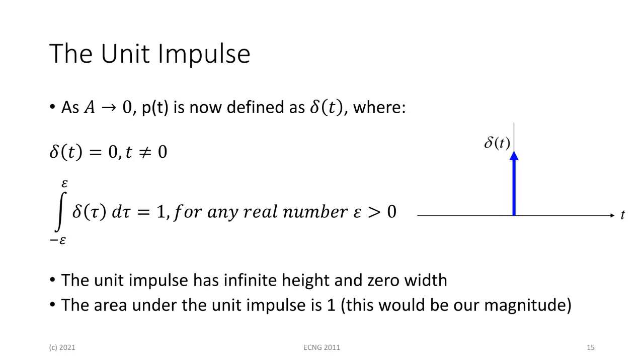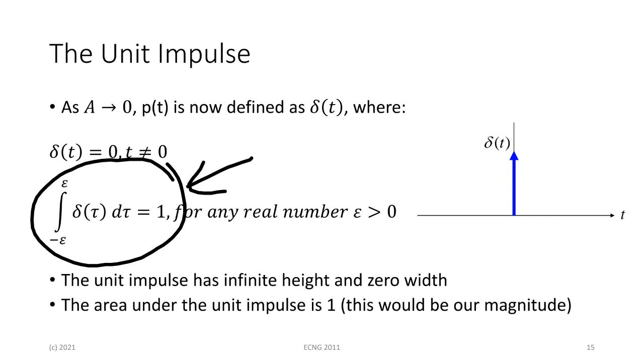It's a mathematical definition. So if anybody asks you outside here, what is a unit impulse, or what is the impulse function? The impulse function is not delta t equal to 1 at t equal to 0. Delta t is really defined by that circle here. It is a function whose area is 1. It's infinitely narrow and infinitely tall, but in such a way that its area is defined as 1, and we call that a unit impulse. Yeah? Fair enough?